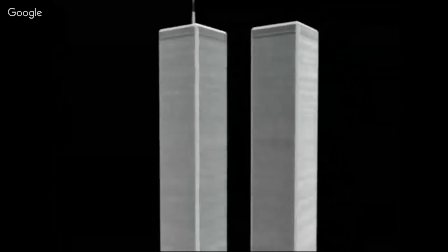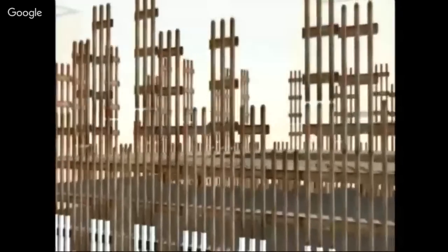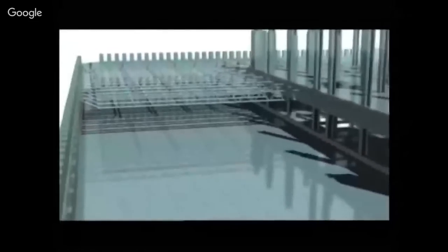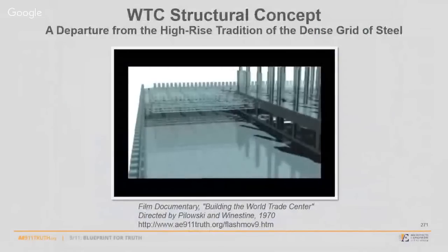But what they did with the Twin Towers was to push most of the columns out to the perimeter in an exoskeleton. This is an innovation at the time, concentrating the core columns around the elevator shafts inside and creating this 3 tall by 3 vertical by 3 horizontal network of welded exterior perimeter sections, and the core columns, almost solid steel, 52 inches by 22 inches at the bottom, thinning to 1/4 inch or 3/8 at the top. And in between these sets of columns spanned these lightweight steel trusses, 60 feet of open office planning, which is what was achieved here.